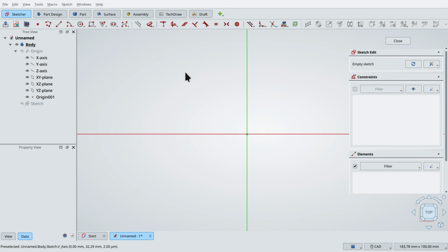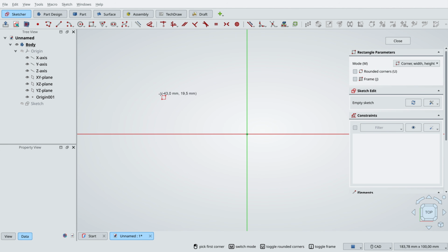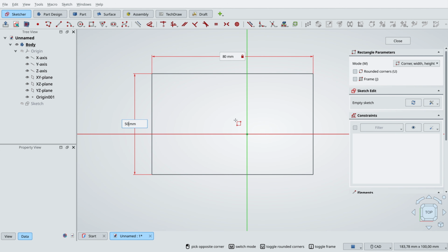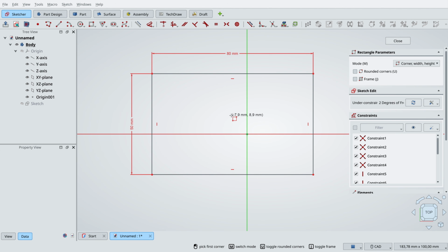We're going to draw a rectangle with a circle inside. First, select the rectangle tool. To draw it, just left-click once. You'll see the 2 dimensions appear. By typing a value, let's say 80, the length locks in. To move to the width, simply press Enter or Tab, and then you can enter a value like 50. Now just press Enter or left-click to confirm the creation.